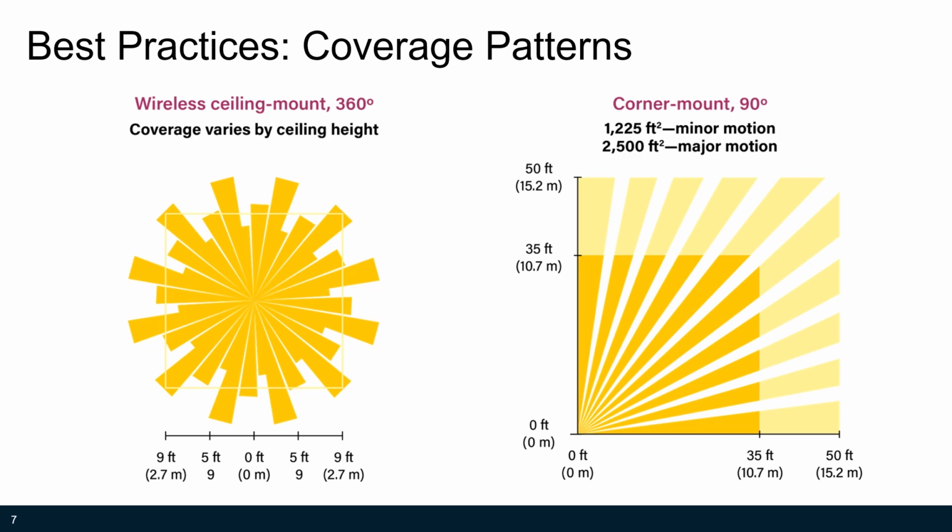Poor sensor placement could allow a sensor to see occupancy in an adjacent space, keeping lights on that could otherwise be off. Too often, the design of the lighting controls is an afterthought or left up to a contractor to determine at the time of install, particularly in retrofit applications. However, with all these design elements involved, it's easy to see why a lighting practitioner should be involved in the process. Sales reps or manufacturers frequently offer design services for both lighting controls at no cost, but this service must be requested prior to system installation.